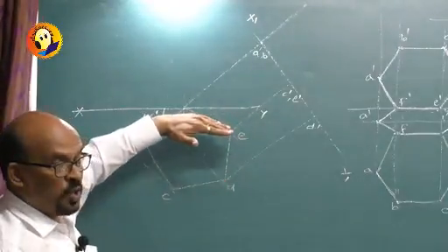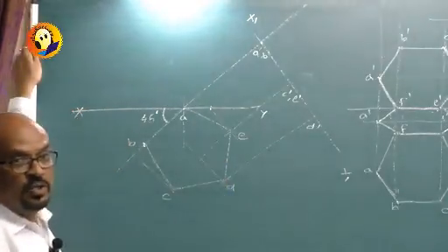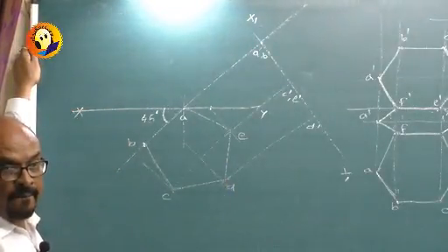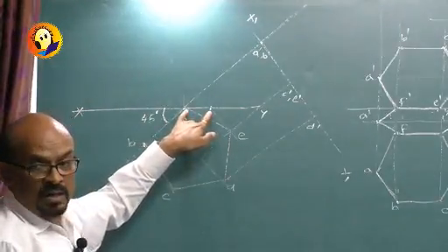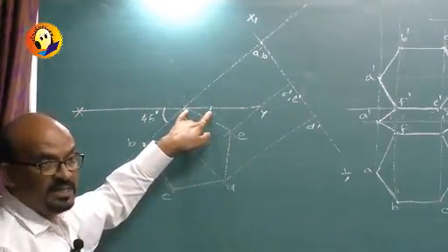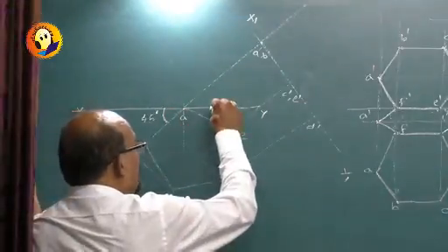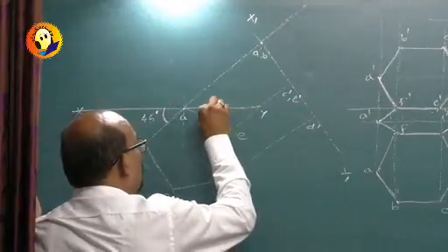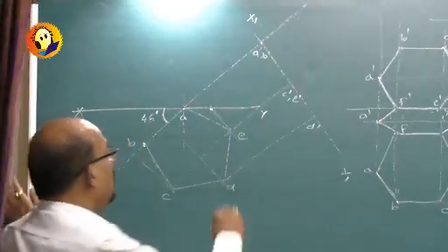And where should it stop? When point E also reaches XY, it should stop, because plan of AE should be on XY. AE is going to be in VP. So we should rotate till the point E reaches original XY. So we found how much E should move.